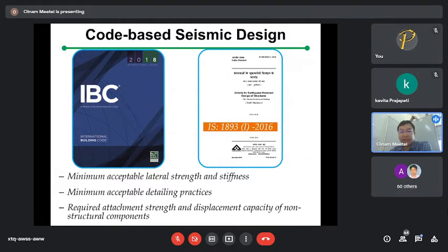Okay, it does not mean that we design the structure in displacement and cross-check in displacement. It's not like that. Whatever design we did, we did based on force only. But the cross verification and the performance objective are defined in displacement. Please make this criteria clear.